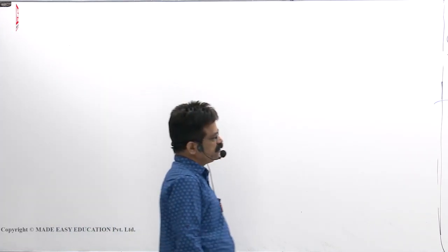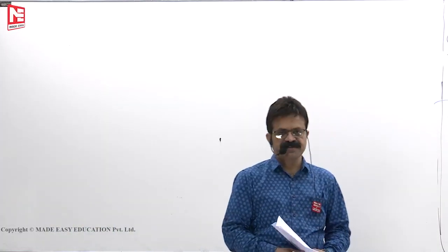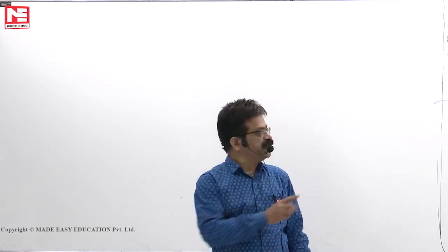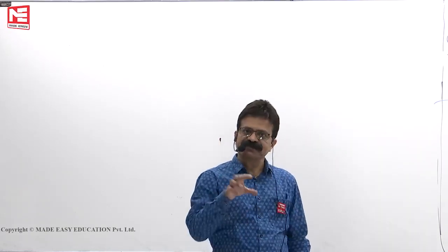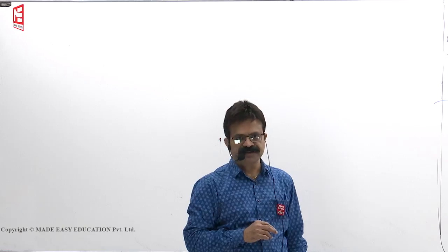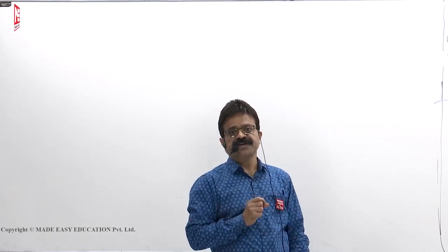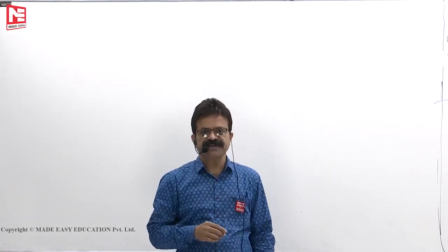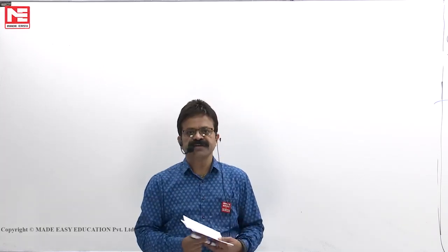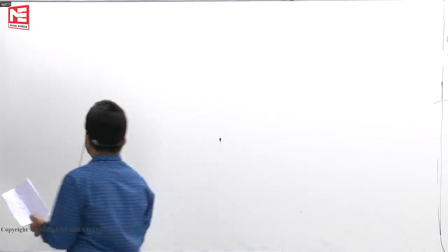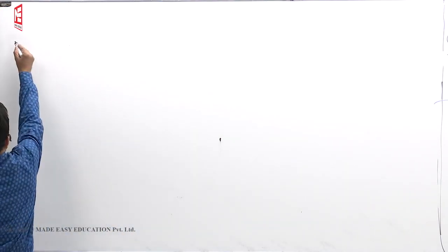Now we have seen if you have a simple truss or a compound truss, by inspection itself we can detect whether they are stable or not. But for the case of complex trusses, we cannot identify by seeing them. So we go for the zero load test. That we see as a second point.